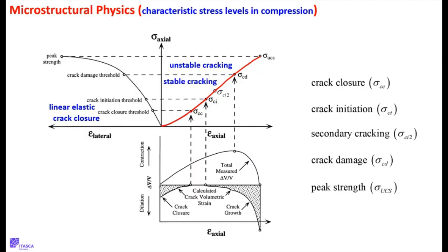And your interpretation of the results is assuming you have uniaxial stress, because that's the interpretation that the experimentalists have in making sense of that, because they're using continuum theory. So they're thinking about everything in terms of stress and strain. And so that's why in rock mechanics, you almost always use aspect ratios of two or more.